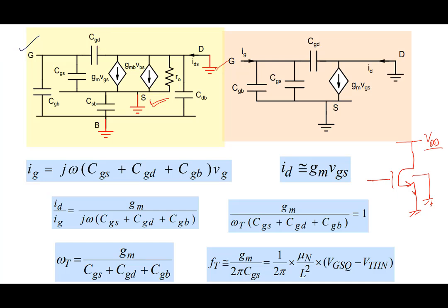And the usual voltage controlled current source, GM VGS. And this term is not there because body and source are both grounded. GM from the body side, if there is any change in body to source voltage, that can also cause a small signal change here. So this is not there here. All right, so for this case we are talking about this situation here, okay? So this small signal model then simplifies to what you see over here,